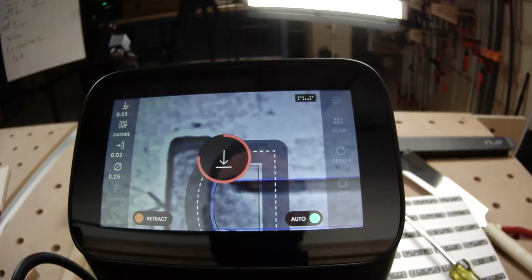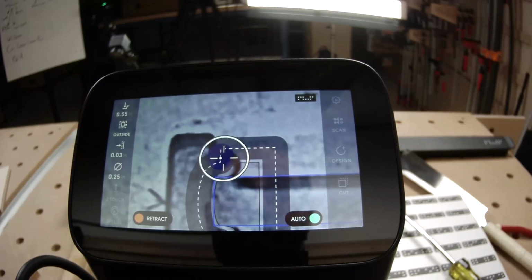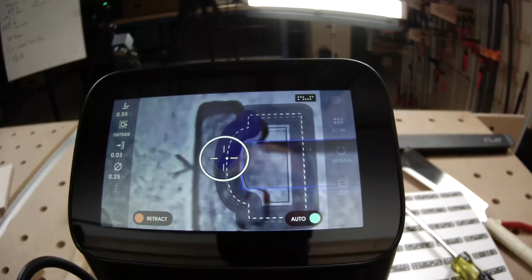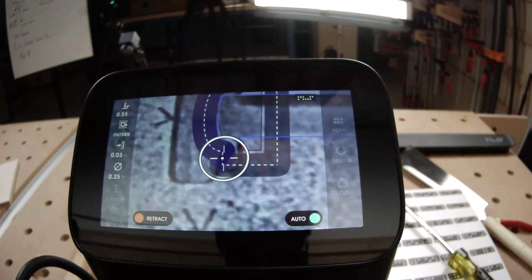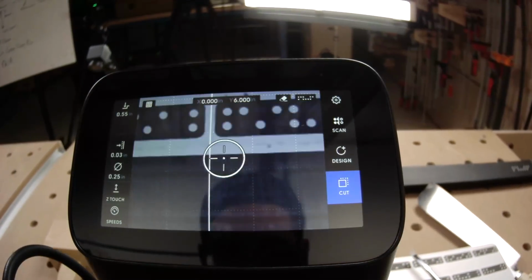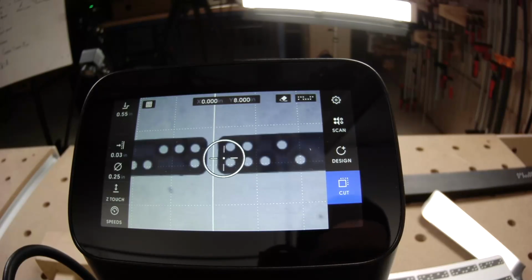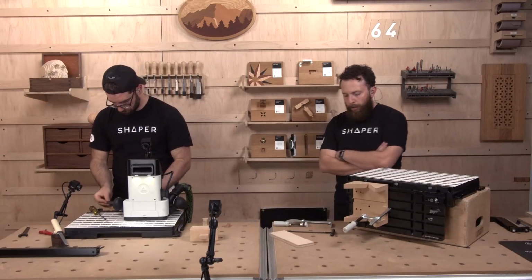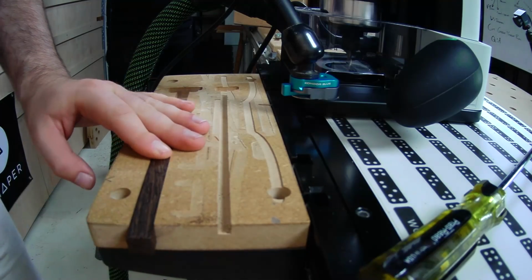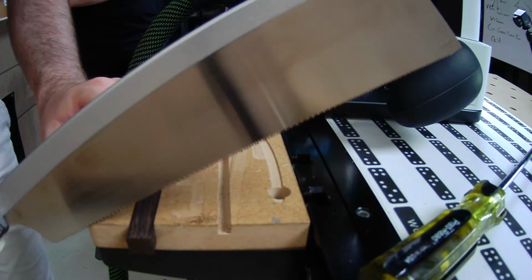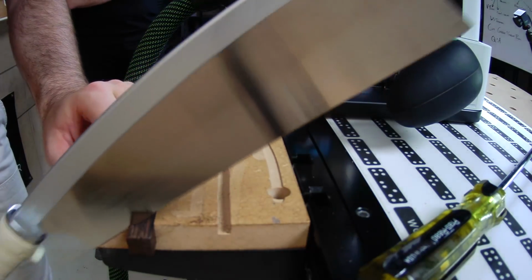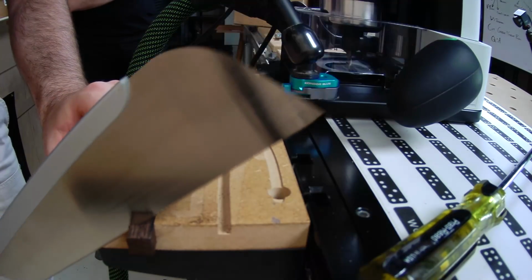So you see that erase button that's next to the marker health indicator on the top right hand side of the screen. You can tap that, and that will clear all of the cut history that's in a workspace. So careful if you want to keep the cut history, obviously, but if you're doing repetitive cuts on a fixture, it's really nice to be able to get rid of that so that you know what you've done, especially if the fixture is a little more complex than this one. You can keep track of the work that you've done really well with that cut history.